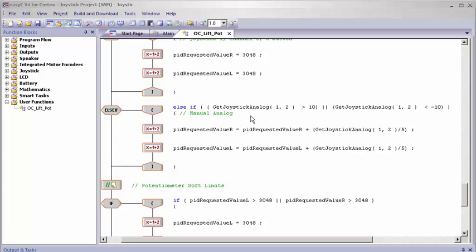So what is this? Why use it? It is joystick control using potentiometers. And there is a joystick control that you can use, but the issue is you cannot put limits on the normal joystick control unless you use a limit switch. So with this, you can set limits on the potentiometer instead of actually having to put limits on your robot. Otherwise you have to put limit switches and worry about getting those in the correct position. But instead you can just use potentiometers as limit switches.